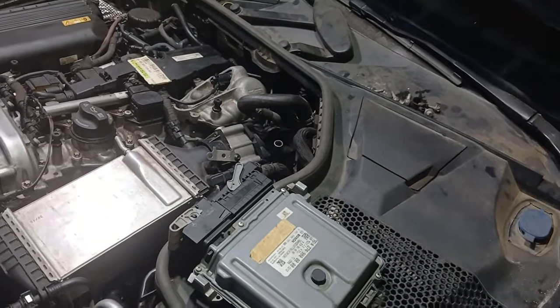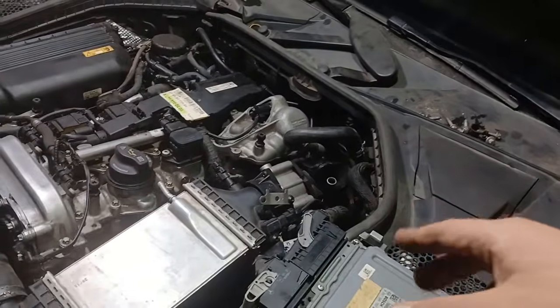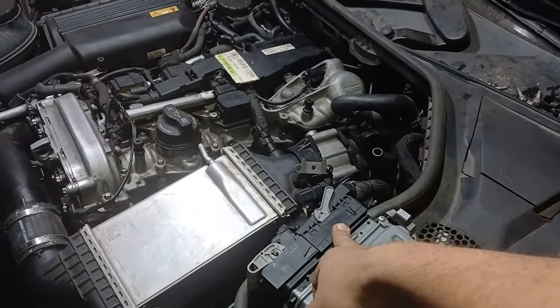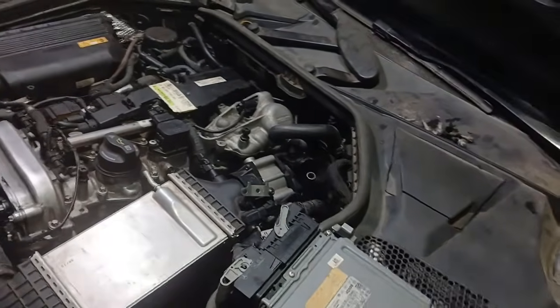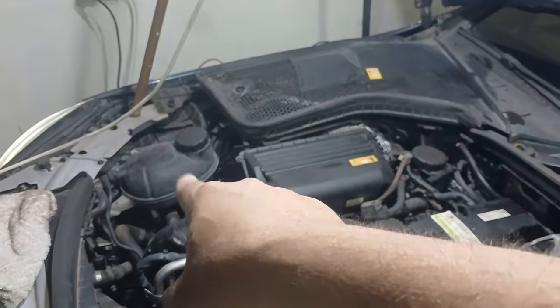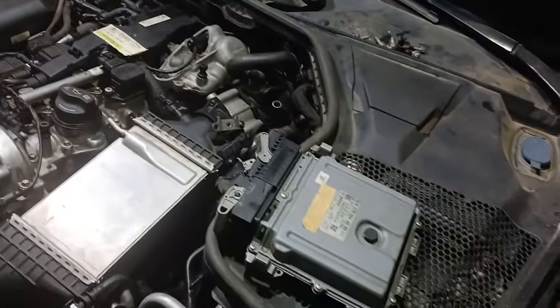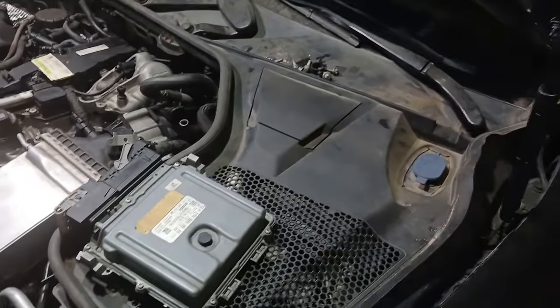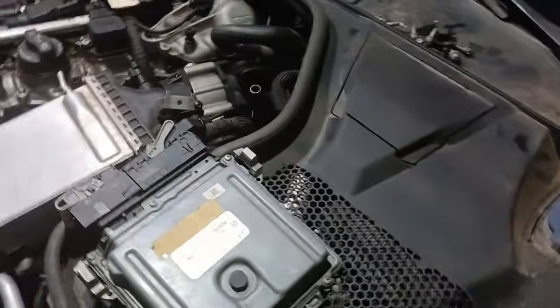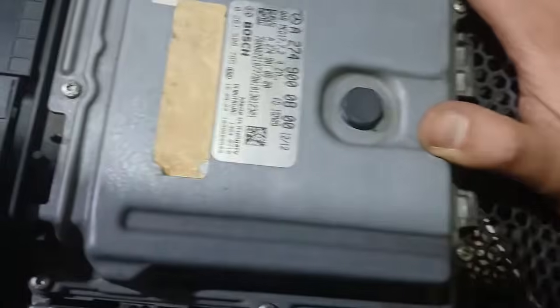We checked it. I checked it on WIS, and we have continuity. I think, as I remember, from bin 23 or don't remember exactly, but anyway, we have power, and the pulse width is connected here, and nothing on the wiring. So I suspected the DME or the engine controller. So here we have the original one. Also, the car starts successfully, but the turbocharger is not working.